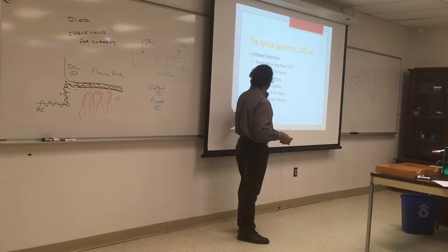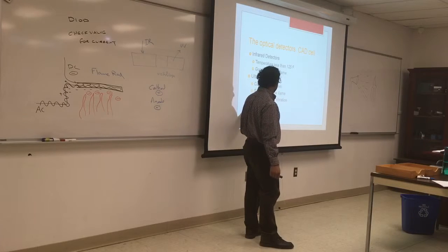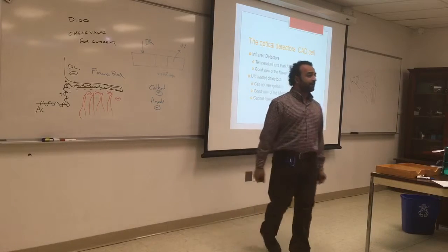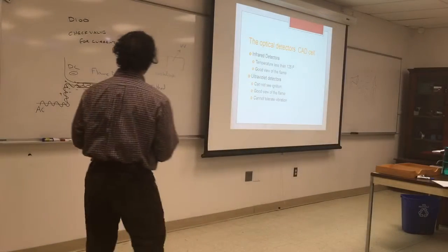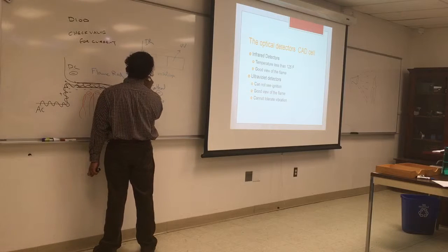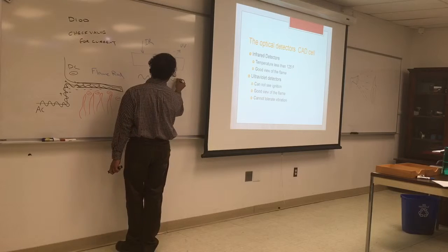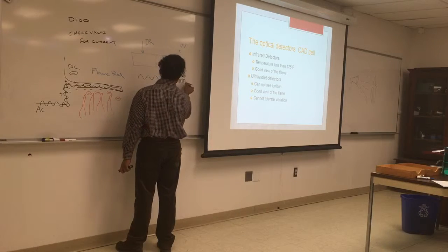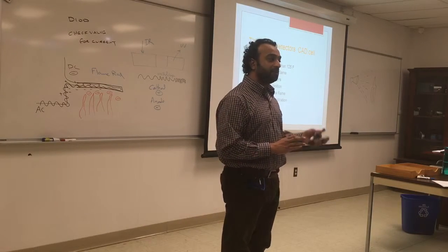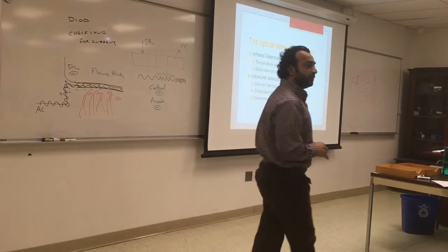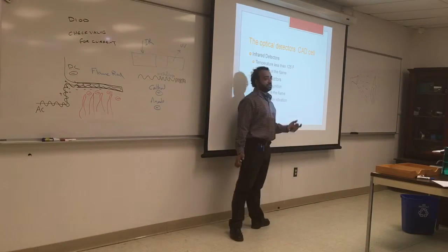Ultraviolet detectors cannot see ignition, they only see the flame. They also require a good view of the flame and cannot tolerate vibration. If you think about it, infrared is lower frequency. This is the frequency here, here it's a bit smaller, and this is getting way smaller. If it's a wave, and we have some kind of vibration in a similar wave, wouldn't you think that will interact with it? So that's why they cannot be in a place where there's a lot of vibration.